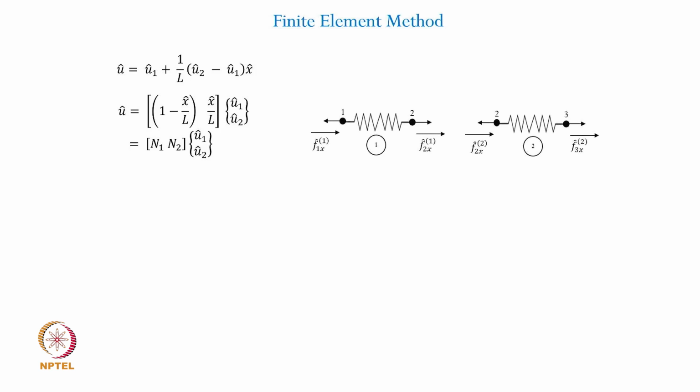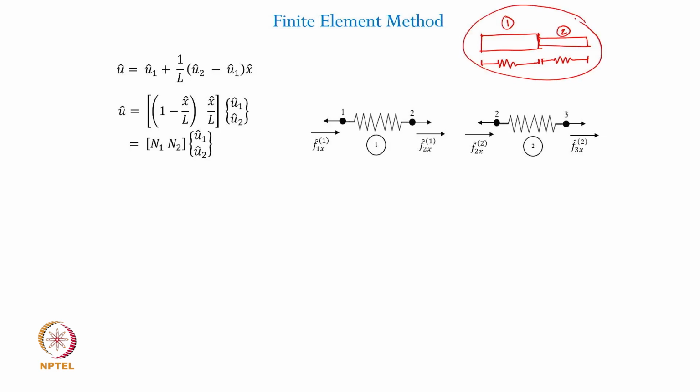And now, suppose that this propeller shaft, as you saw as a step shaft, was discretized just into two segments or two elements, like element number 1 and 2, each having constant cross section individually, but one has different cross sectional dimensions as compared to that of 2. If we assume this to be representing one finite element and this one as a separate second finite element, they will have to be assembled together to recreate your original entire propeller shaft.